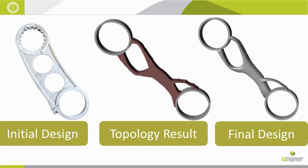Some of the options inside Inspire, like topology, topography, lattice, gauge, and how some of those combine. And I do want to add one final thing, that the design on the right that you see, they have to still be analyzed, and we can do that inside Inspire as well. You can analyze it, make sure that the factor of safety is good, that it's a part where the minimum frequency, the first natural frequency, is higher than a threshold limit that you set. All of that can be done inside the same interface before you export the model as, let's say, a Parasolid file.